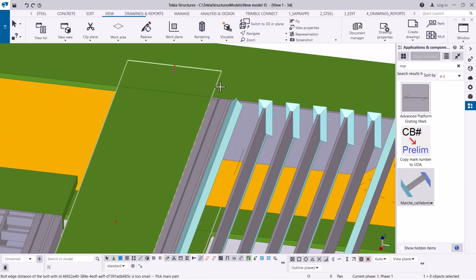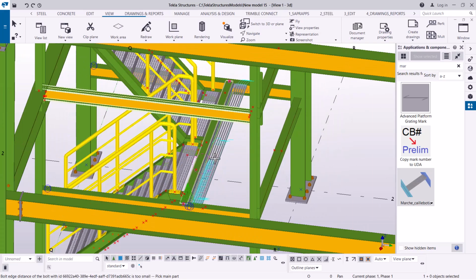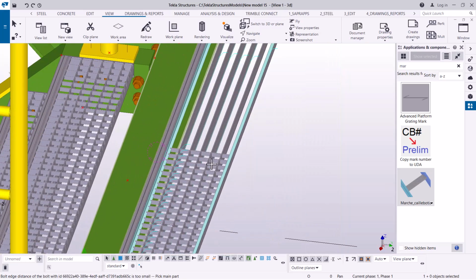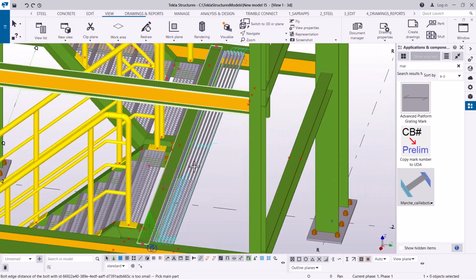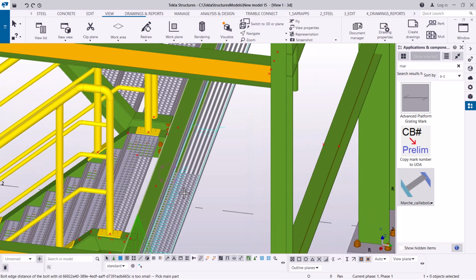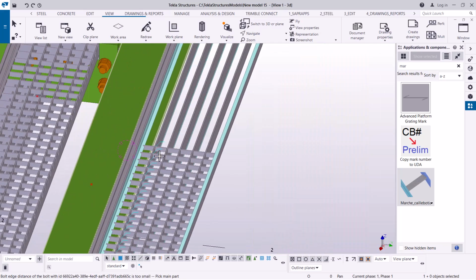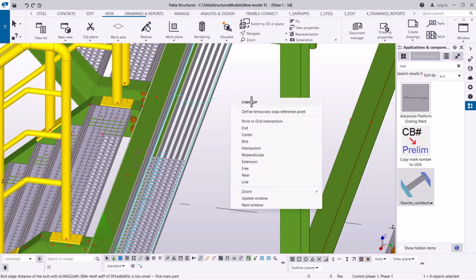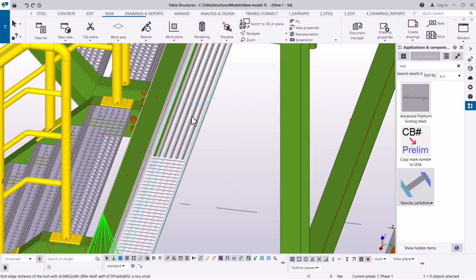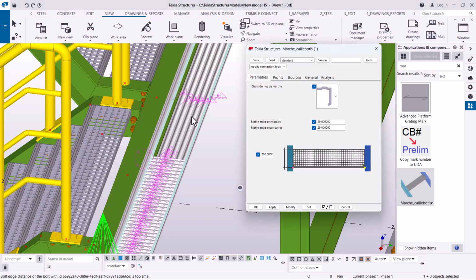What I'll do here is quite simple: add the width and also define the full length so that we have these members cutting across, going all the way to the other end. So if I come here and double click on it to get the dialog box in place, I'll be able to key in here 900 instead of 200.